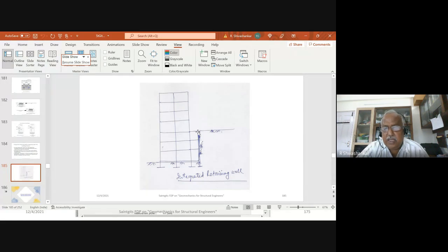So these slabs, RCC slabs, are designed as two-way slabs, but not for vertical loads like roof slabs, but for lateral loads. So you can have a soil, footing, superstructure, retaining wall interaction problem. What it means is that the weight of the building is utilized to resist the lateral forces.